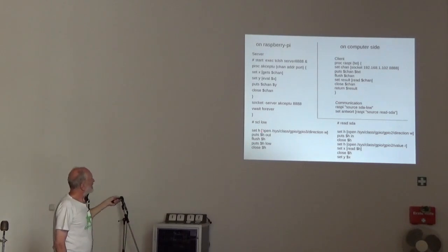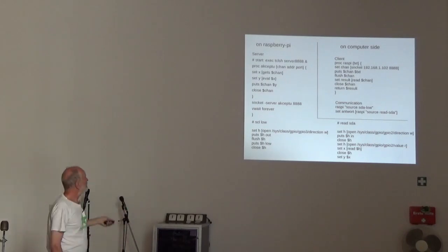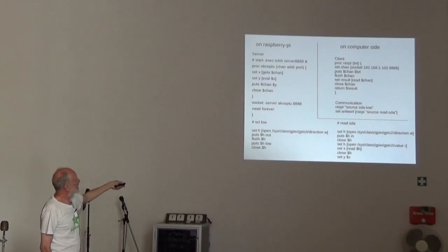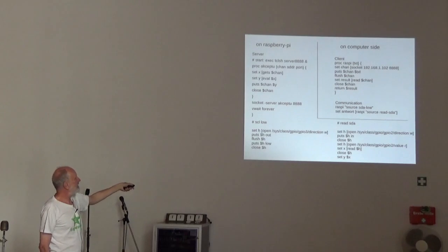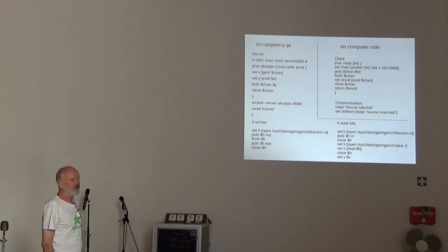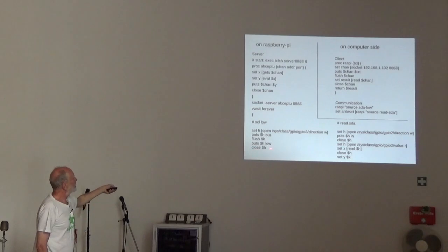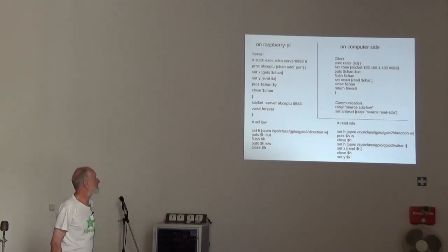Then it will carry out the program SDA low, which is just we open this class GPIO, GPIO3, direction right, put it as an output, flush it, then put the level low to it, close,